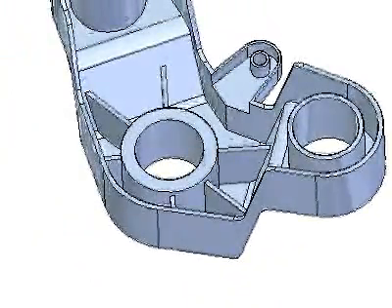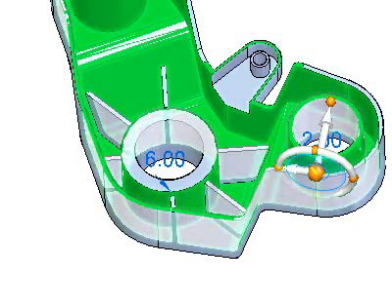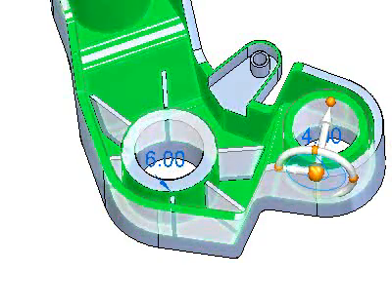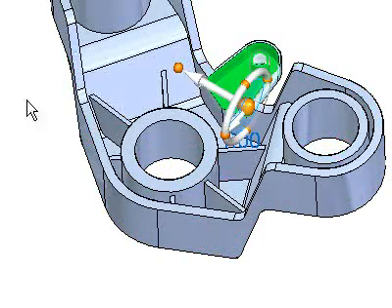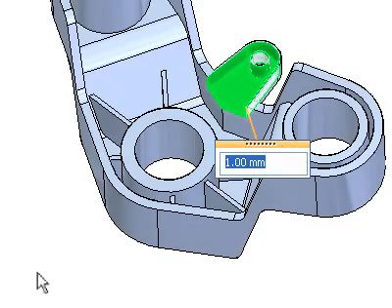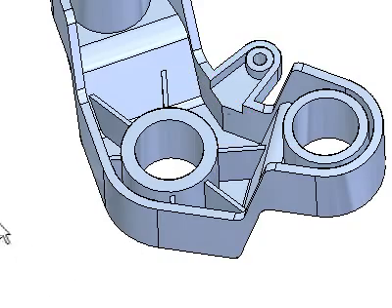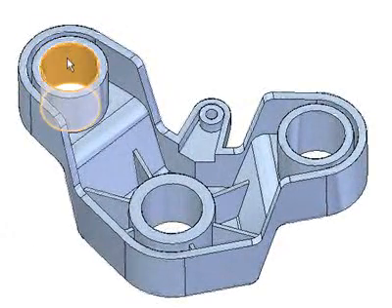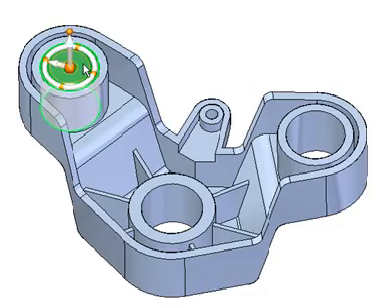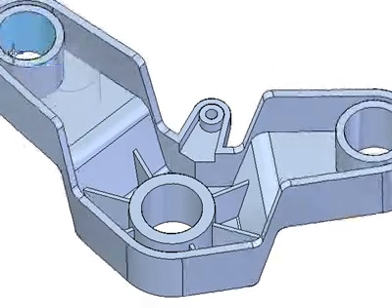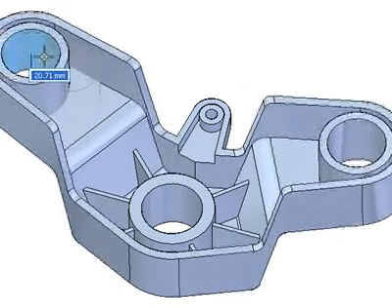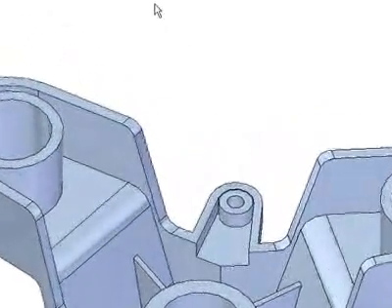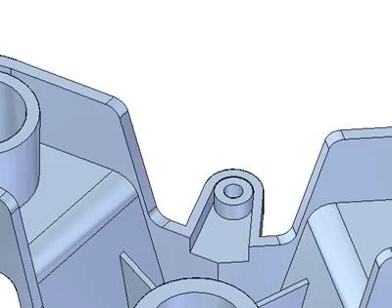Thin-wall operations are procedural, so you still have edit control without complete model regeneration. Watch as we change the wall thickness and the model instantly updates. Because of this technology, larger, more complicated models will also update with the same nearly instant speed. To further demonstrate this fast performance, let's make a change to the entire model. Since the part is just roughed in, we can modify the arm by moving one of the original mounting holes. As the edits are made in real time, see how the model stays symmetric and the wall thicknesses are maintained.